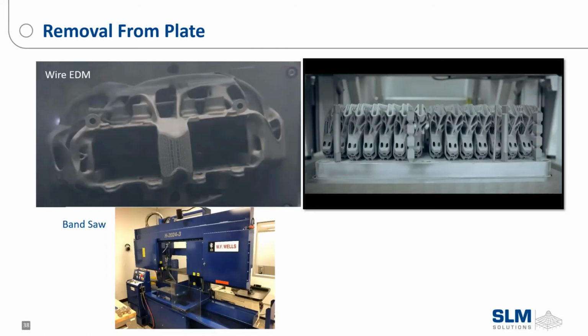Another thing is hot isostatic pressing. HIP applies high pressure and high heat to the workpiece, or the part in question. We're not actually melting the material, but we get it to a point where it's so soft and the pressure is so high that all the voids, like we can see here on the right, will be closed up.